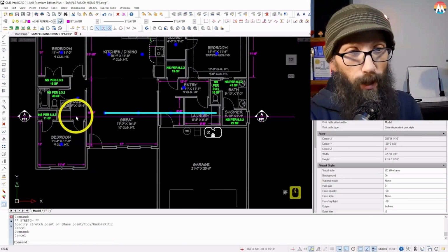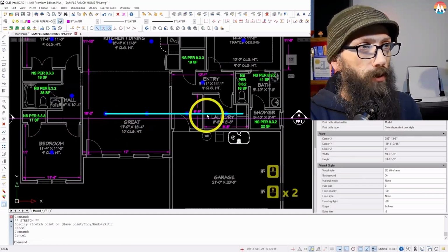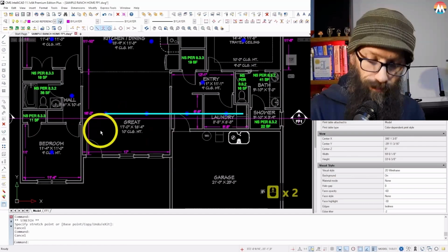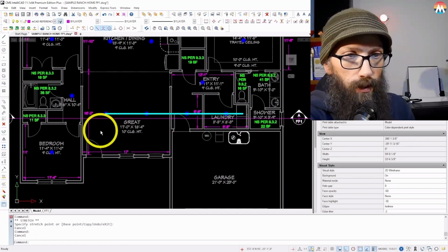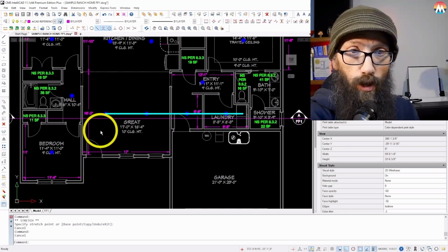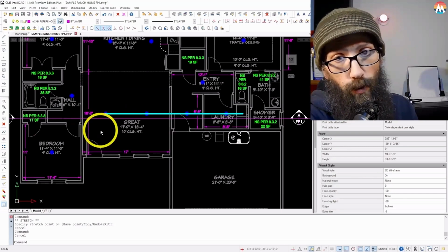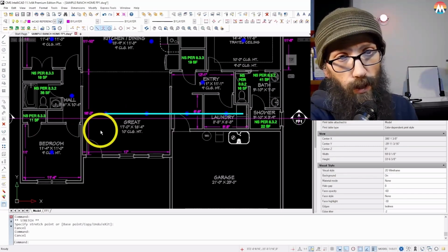Okay, and one thing, I better back up. You may be wondering, why did I decide to run the pipe that direction? So one of the things with this sprinkler design is that the building, pretty much the structure, for the most part, dictates the way that we want to run our piping.